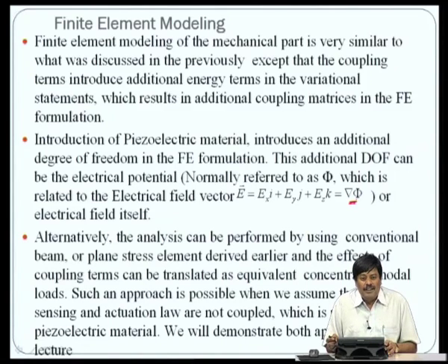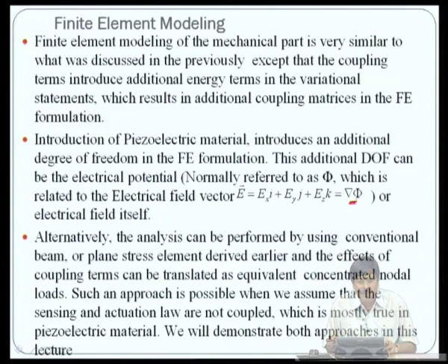Alternatively, since the sensing and actuation law are not coupled, analysis can be performed by using conventional beam type elements or plane stress type elements or even plate element derived earlier, and the effects of coupling terms are translated into equivalent concentrated loads onto the beam structure. The conventional beam, plate or plane stress element can be used to solve both sensing and actuation problems. We will deal with these two and see how each of them can be used in this lecture.